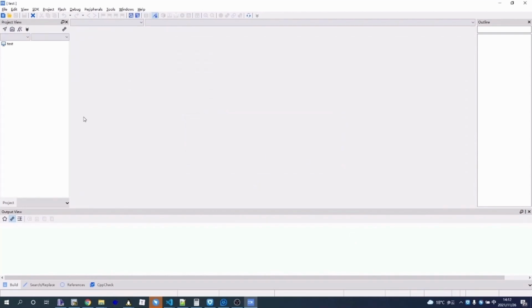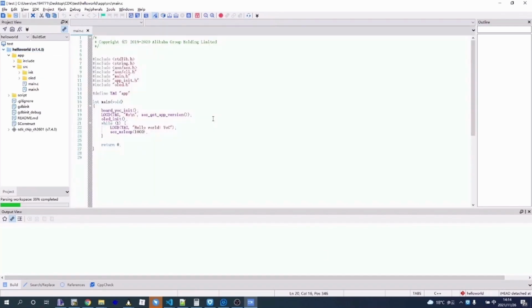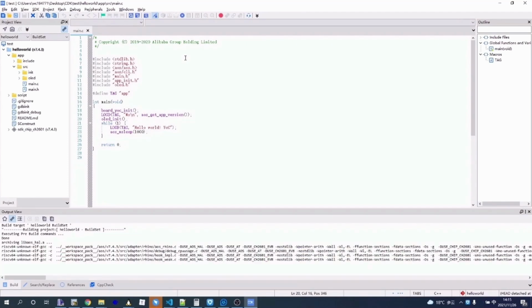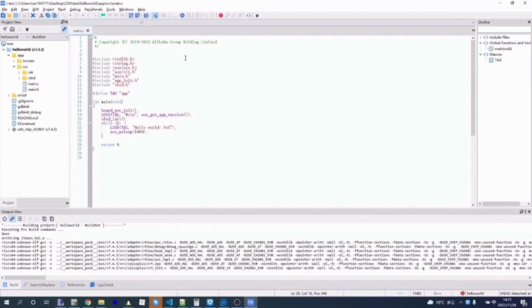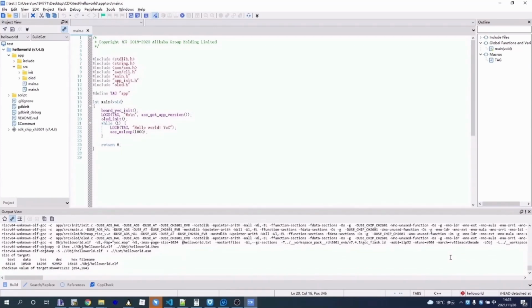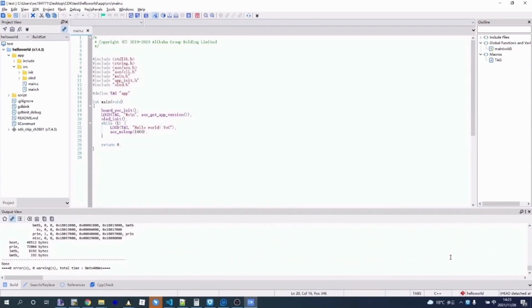Then you can download the firmware into the RVM-2601 board by clicking the Download icon. Open the Serial Client tool and set the baud rate to 115200. After pressing the reset key on the board, you will see the hello world YoC string in the serial window. That means you have already brought up the YoC basic system successfully.